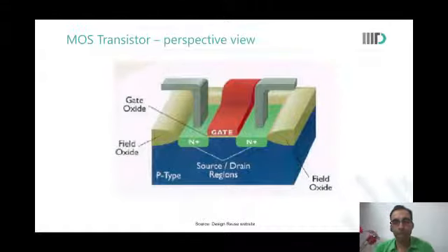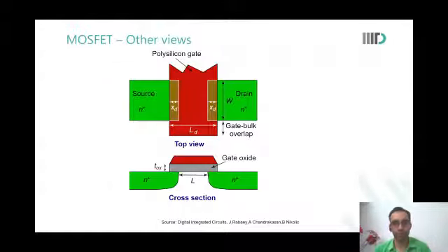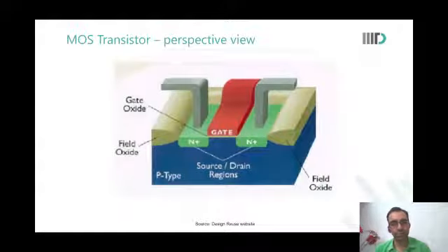Okay, sir. So, yeah, I got that when there's no inversion layer, just a depletion region, effectively there are capacitors in series. So the effect is that your capacitance gets lower. Yes. But when there is an inversion layer, the region of the substrate right beneath the silicon dioxide acts as an n-type substrate, right?